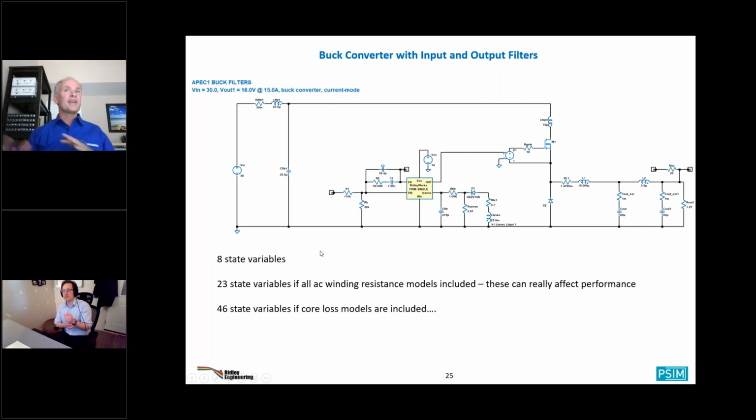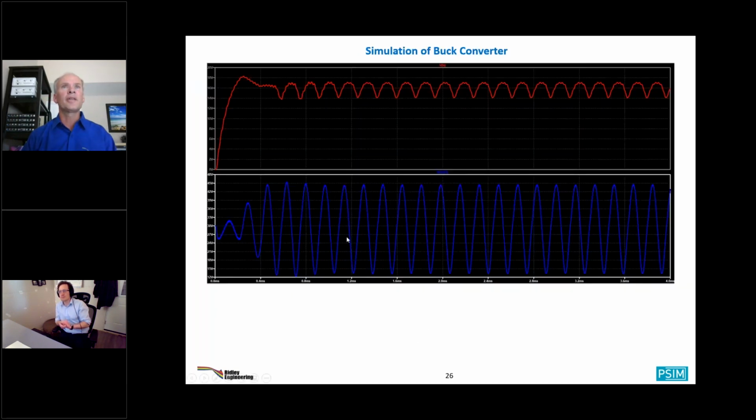Now, if you give me a second order converter and you say time domain, frequency domain, it's like, yeah, okay. But if I've got this going on in my converter, this is my time domain simulation, I have no tools for debugging this and fixing it. And that's where the Bode plots really come into their own. So they're all different tools.